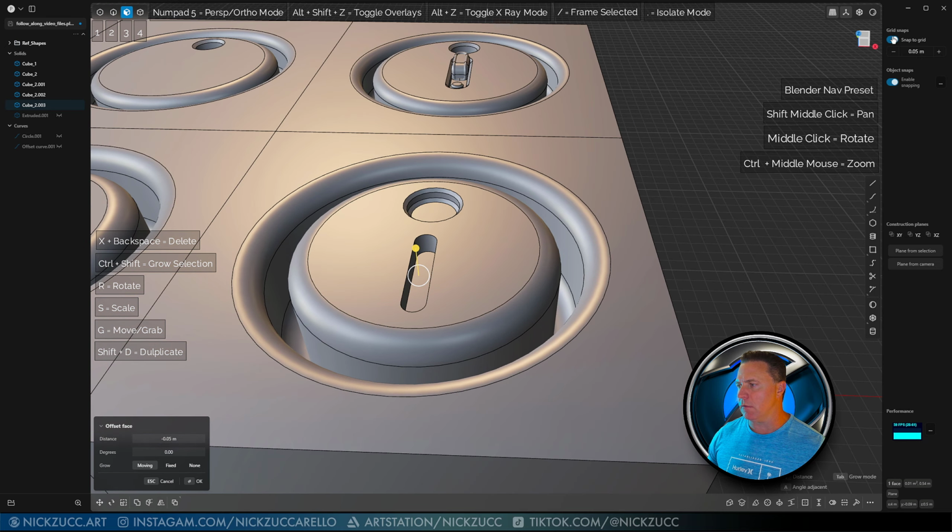So I'll just right click on there, and that'll give us this little part here. And then what I'm going to do is tap 2, select this, and then we're going to go this direction with it, and then just do a fillet. And it's up to you how much curvature you want on this thing. I'm just going to continue on like this right here, and I'll right click on here like that. Okay. So there's that part.